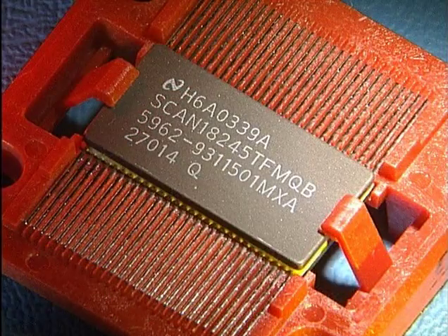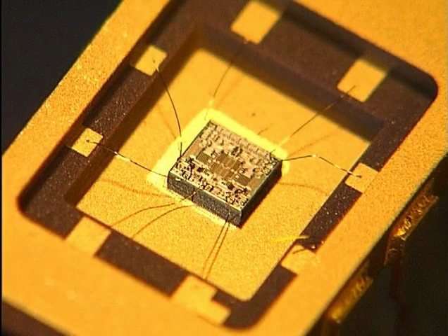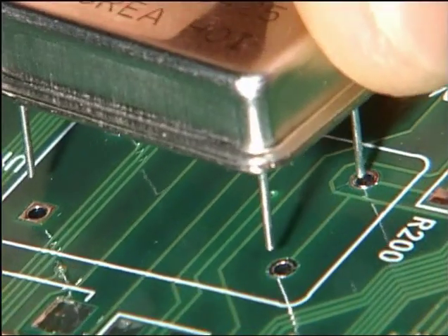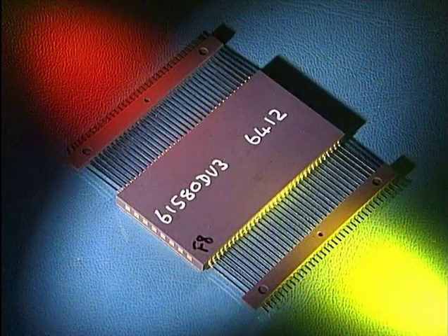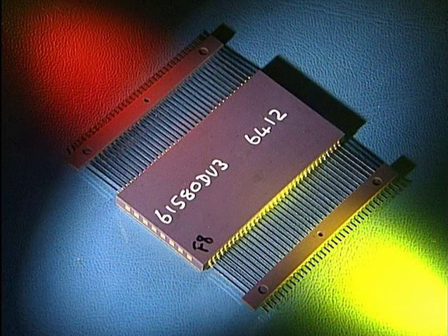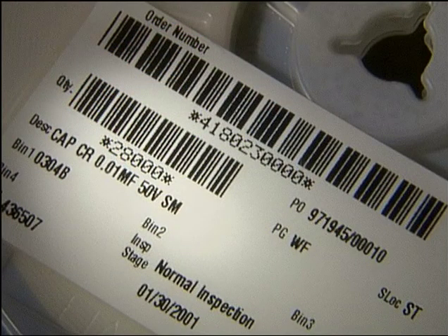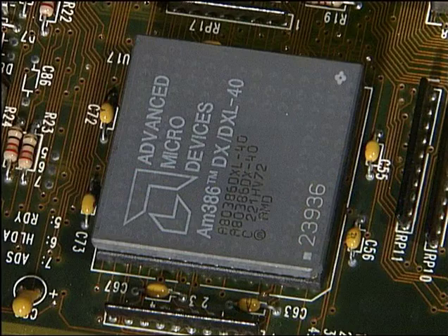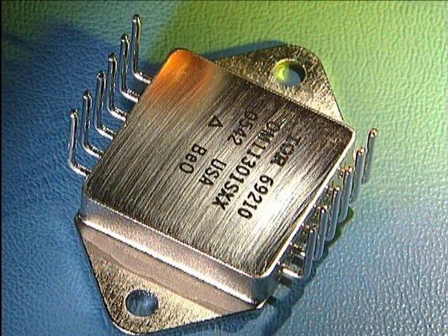At this point, let's examine some of the important factors you'll need to be aware of to begin identifying and understanding components. We'll start with component marking. Every manufacturer of electronic components uses a slightly different system for marking components. This marking will either be on the component or on the component packaging. Typically, this information includes the manufacturer's name or logo, the component part number or ordering code, the lot code, the date code, and the country where it was manufactured.